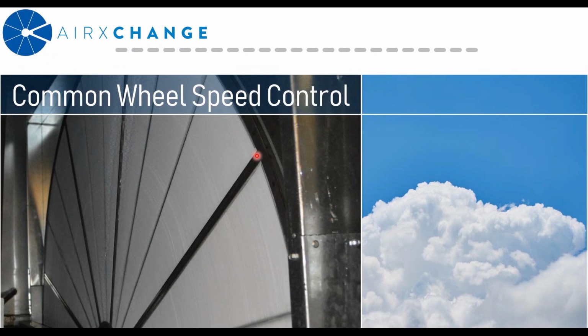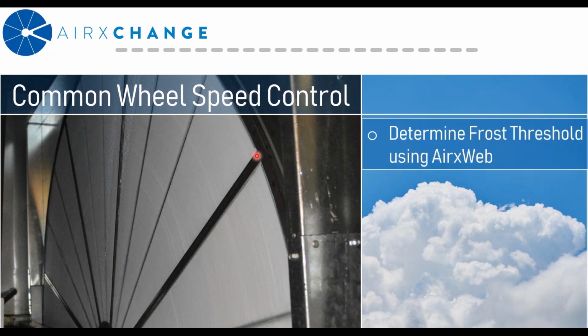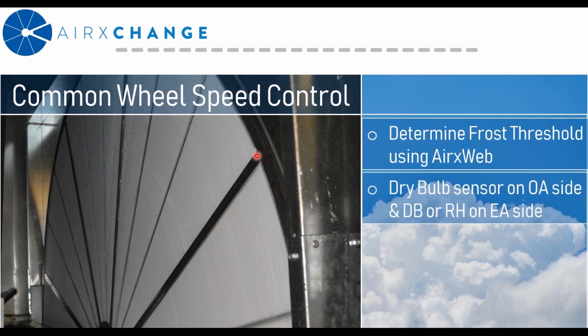So integrating, that should say airflow bypass, I apologize. So once again, integrating airflow bypass into a system, you'd use the Airxchange software to determine a frost threshold. Anyone noticing a trend with that first bullet? Since this process is so similar to wheel speed control, you're going to use the same methods. You would either use a set of dry bulb sensors or a dry bulb and a relative humidity sensor. And you'd also follow the same steps.